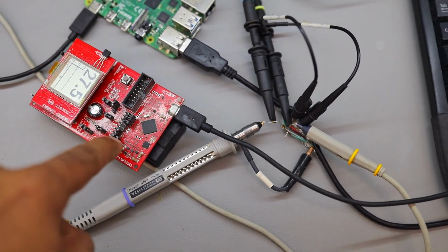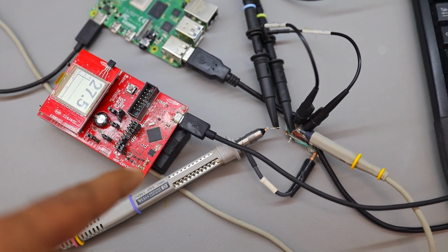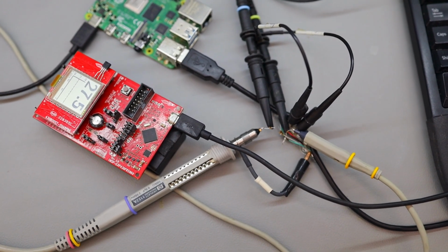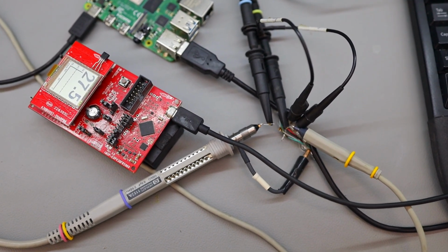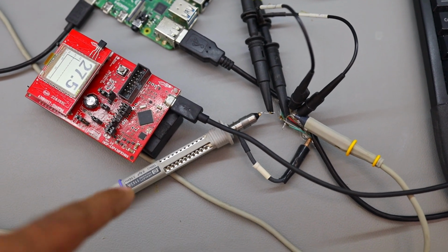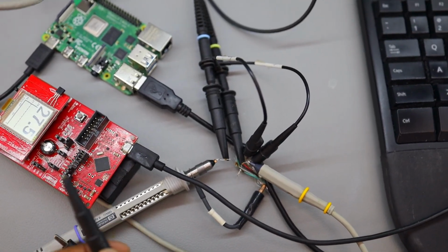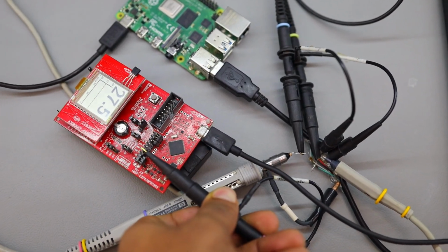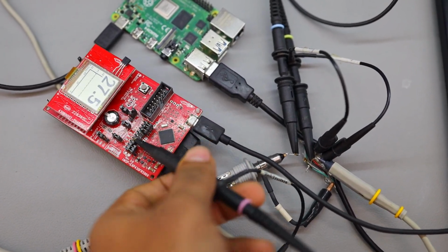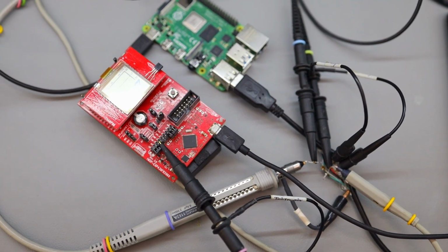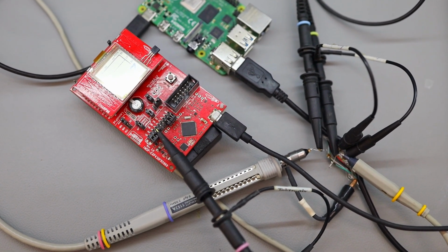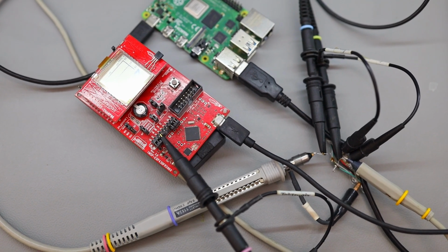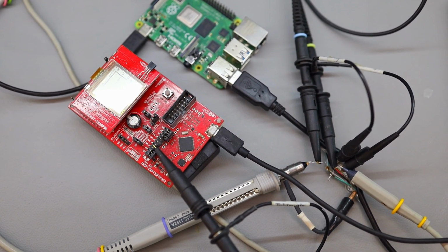So we'll probe the UART as well. I'll show you, in relation to the UART signal being transmitted on the bus, what you see on the USB side. We will do the same experiment. First with the MDO 3000, we will take the third channel of the oscilloscope. So I have taken the third channel of the oscilloscope and I'll connect it to the UART. It is connected now, and now we should be able to see the UART packet being received on channel number 3 while USB is on channel number 1 and channel number 2.